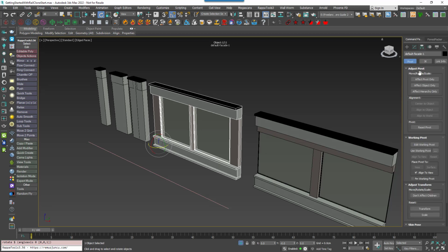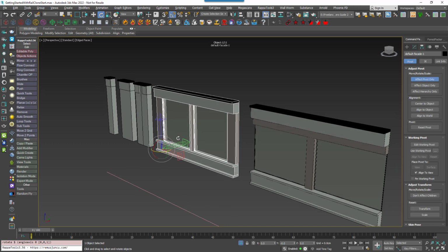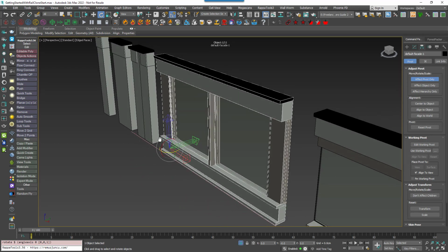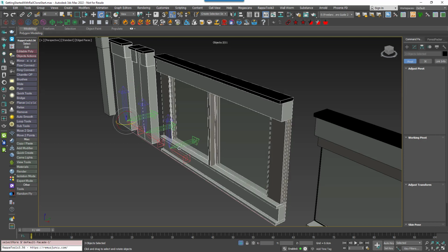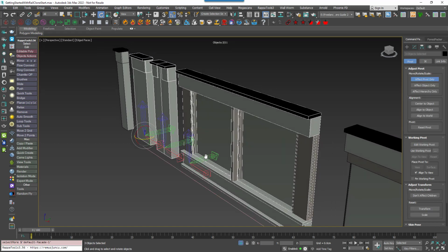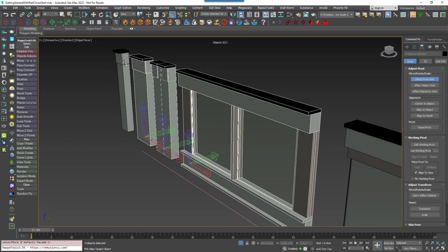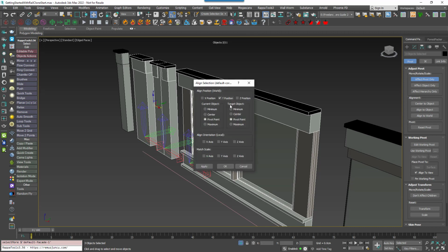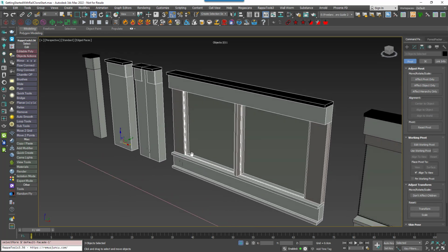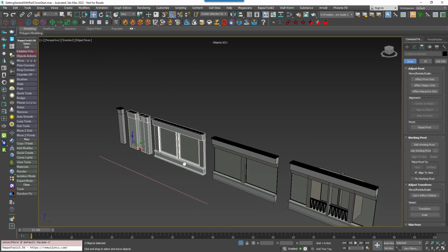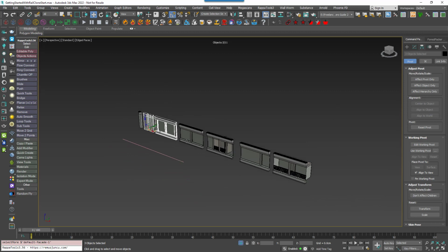As well as orientation, another consideration is the position of pivot points. In order for segments to snap together correctly, it's advised to align the segment on the base object using the local pivot point of the source geometry. This is particularly true on the Y and the Z axis, but less so on the X axis where RailClone's automatic mode is often much more practical. In this example, we'll align the segments using their pivot point on the Y axis, and so to ensure they snap together correctly, we'll make sure all the pivot points are aligned on the Y and the Z axis.